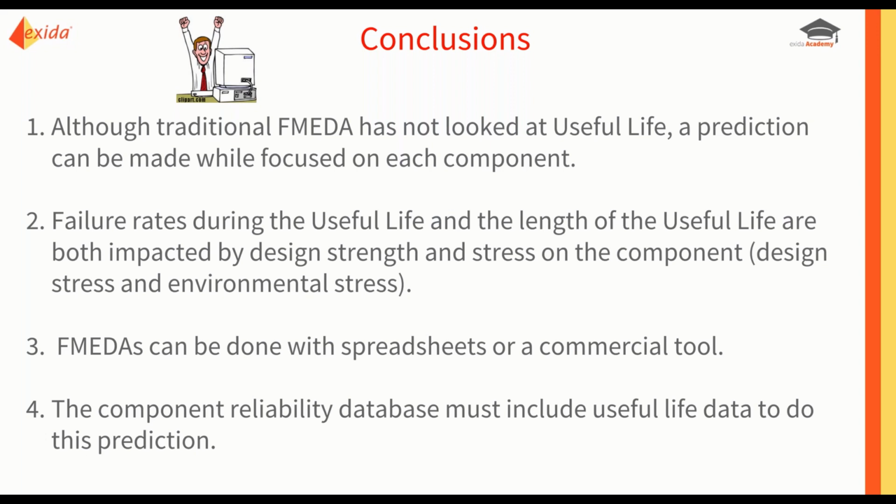Failure rates during useful life and the length of the useful life are both impacted by design strength and stress on the component. And by stress, we mean the design stress. How much over-design do you use? How much margin do you use in your component specs? And the environmental stress, primarily average ambient temperature.